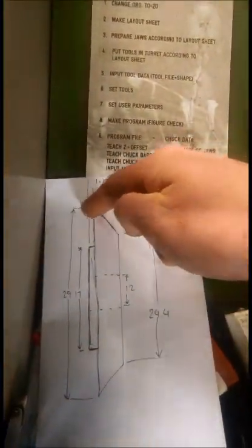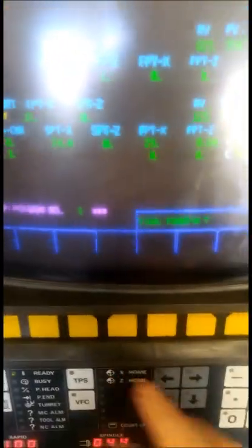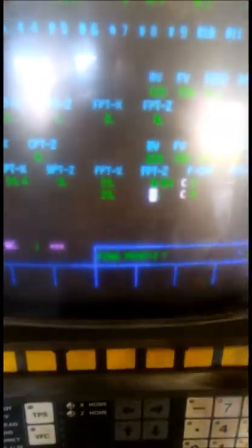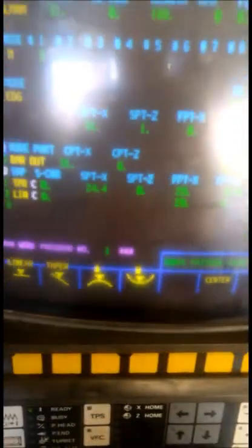And surface, we'll put that at 8 because we want it to be pretty. And then I'm just going to run a line along, just along there, because I'll be grooving the rest of it out. So a line, no starting, keep it at 29, and I'll run it along to say 6. Keep that on 8 as well. Alright, so that's it for that out turning, so shape end.